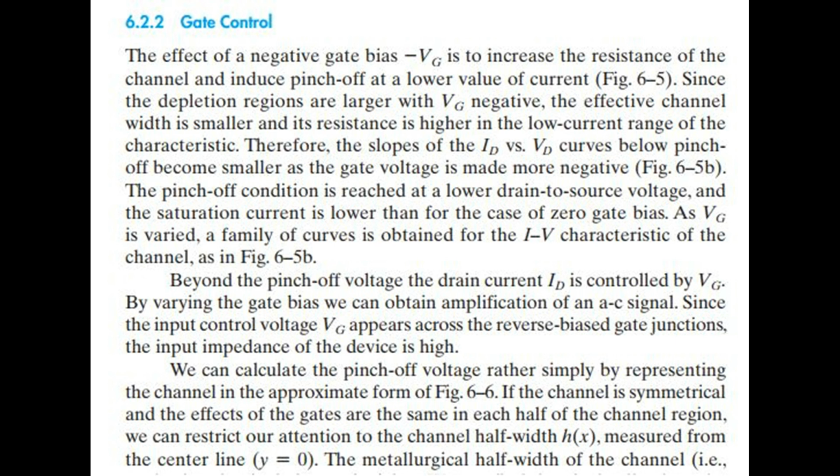Therefore, the slopes of the ID versus Vd curves below pinch-off become smaller as the gate voltage is made more negative, Fig 6.5b. The pinch-off condition is reached at a lower drain-to-source voltage, and the saturation current is lower than for the case of zero gate bias.